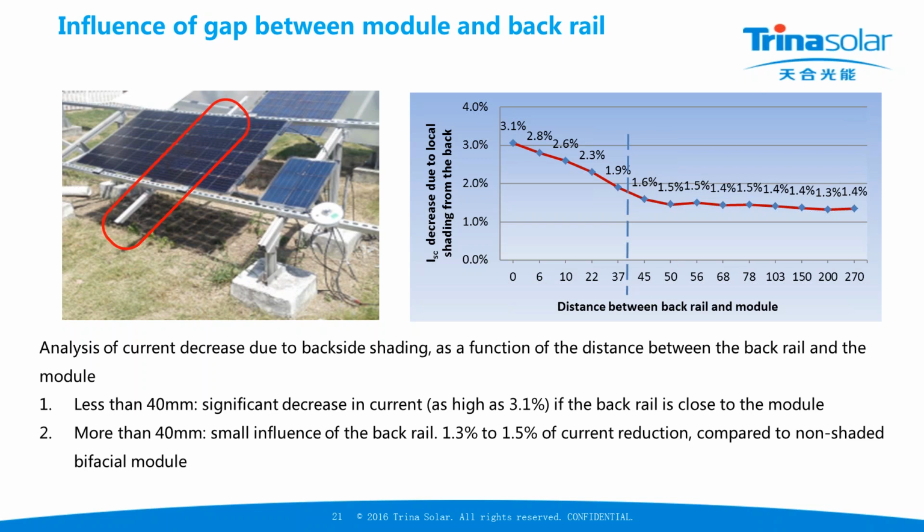So to get up to 35%, which is extremely optimistic, you need to have a very high bifaciality ratio and very good background. So if you have P-type modules with about 70% bifaciality ratio, and you have fresh snow with up to 80% or 85% albedo, yes, it's possible, but you don't have that all year. So over the years, getting 35% energy gain is extremely difficult.